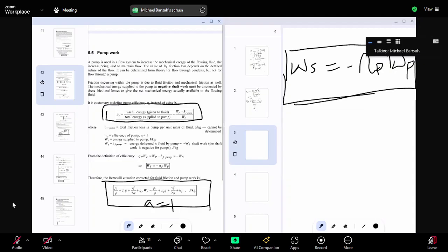That is also considered. Now the HF is not only the friction in the pump. We have to understand that the HF is the friction in both the line and the pump. It is a summation. The fluid flows through a certain pipe. In that pipe, yesterday we concluded that there will be a certain friction, HF.